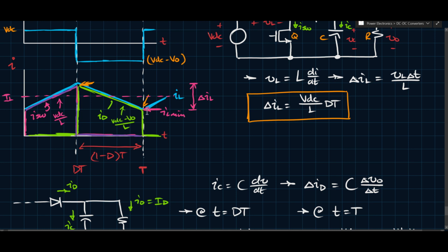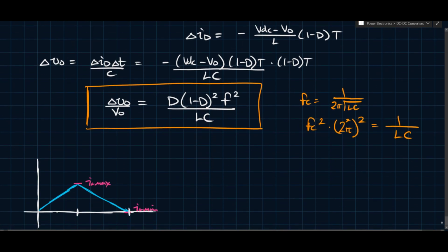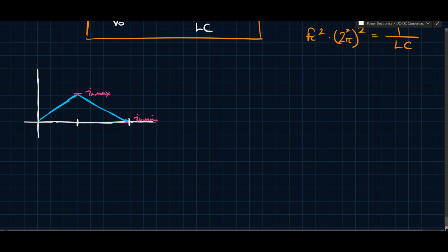And it's not a bad thing. Depending on the application, some people actually want their converter to be in discontinuous conduction mode. It's easier to design for in certain cases. In certain cases, it's not. It's a trade-off, as all things are. But this is something we need to analyze as well. So this is continuous conduction mode. And in continuous conduction mode, we know that the output over the input, or the conversion ratio, is 1 over 1 minus d. And in the discontinuous case, it's not 1 over 1 minus d because the whole situation changes. So this is the boundary, okay?